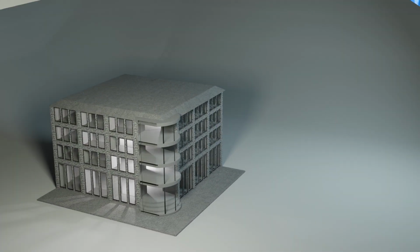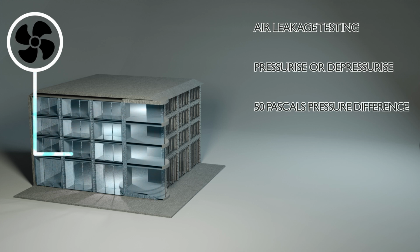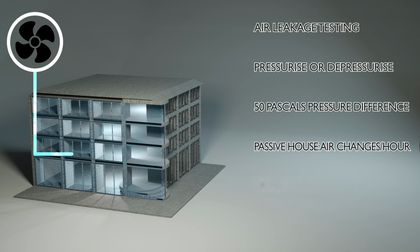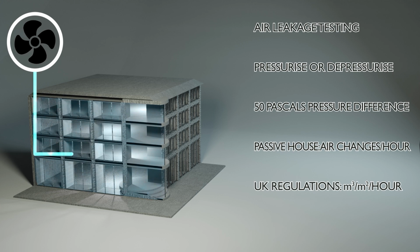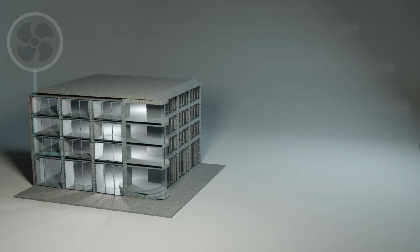The air leakage rate of a building is measured by either pressurizing or depressurizing, and then measuring the flow of air required to maintain the difference in pressure. Normally, a pressure difference of 50 pascals is used for the test, and the result is usually measured in either air changes per hour for a passive house or meters cubed per square meter of floor area per hour for the building regulations. The same pressure test data can be used to calculate results to either standard, but the results are not usually interchangeable. It's also worth noting that air tightness here refers to unplanned air movement. Intentional ventilation openings in HVAC systems are disabled and sealed during the tests.